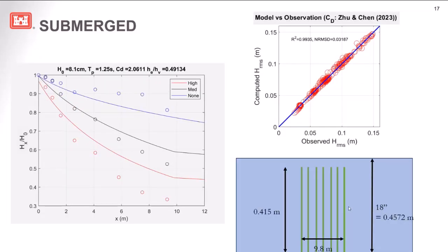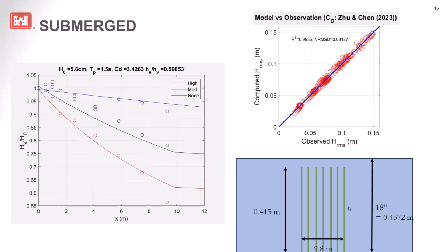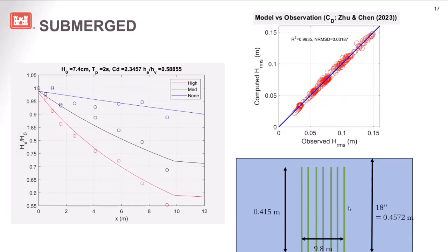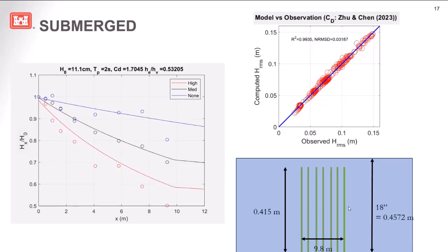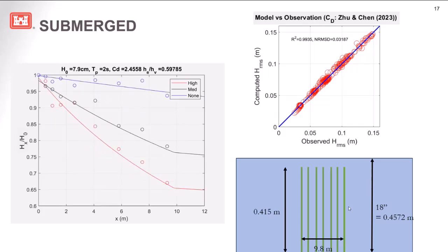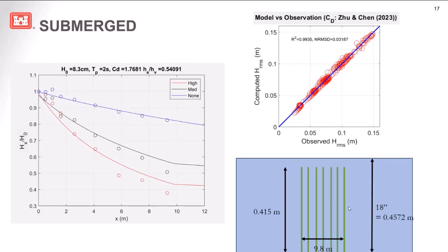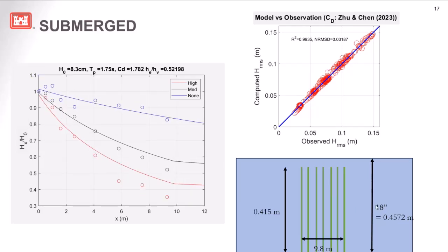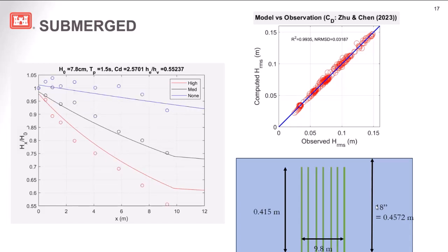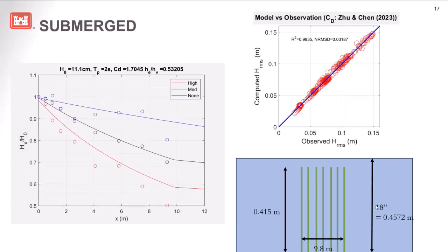First here are the simulation results with a water depth of 18 inches. We have the greatest spread of incident wave cases here and a really good performance with an R-squared value of 0.99 and normalized root mean square deviation of 0.03. With higher waves, we do get some vegetation emergence. And on the left, we're cycling through normalized root mean square wave heights with the simulated represented by the solid lines and observed measurements in points.